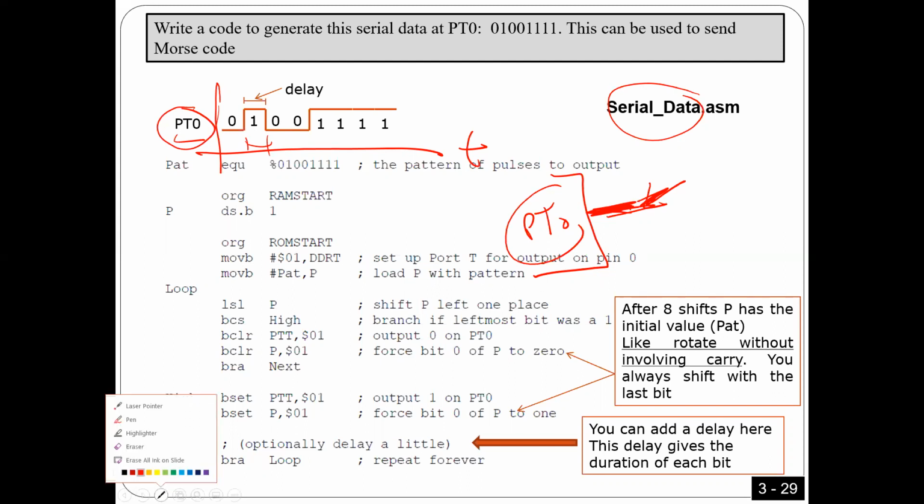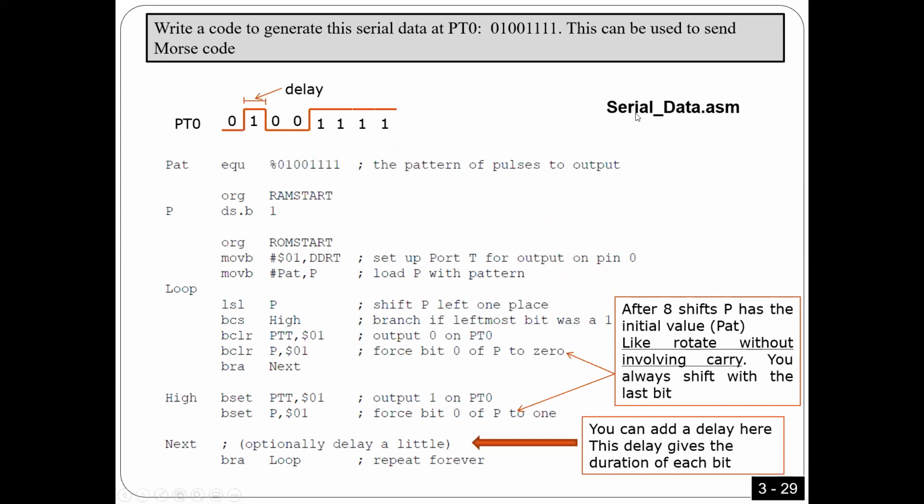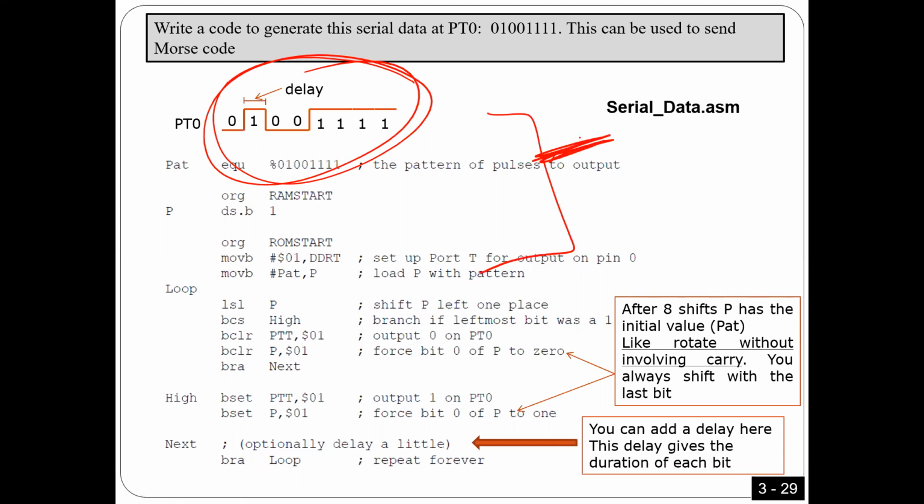What I want to do in this interesting program is output this code, or this information, serially on the pin. If I look at this pin, I have to see something like that. However, if you output this information only one time, it's going to be too quick for you to see, because the scope trace is going to disappear quickly. That is why I ask you to repeat.